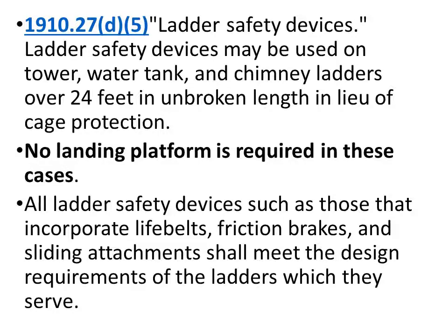Ladder safety devices may be used on towers, water tanks, and chimney ladders over 24 feet in unbroken length in lieu of a cage. So that would be a self-retracting lifeline. And in this instance, you don't need to have a landing or a platform because you have a way in which somebody can rest against the ladder safety device or their climbing device.